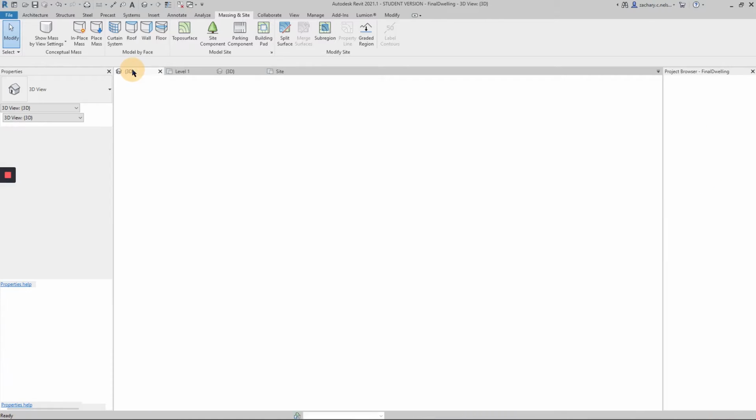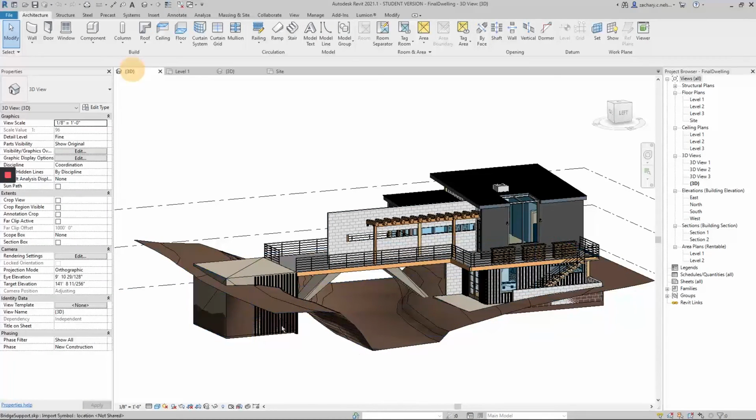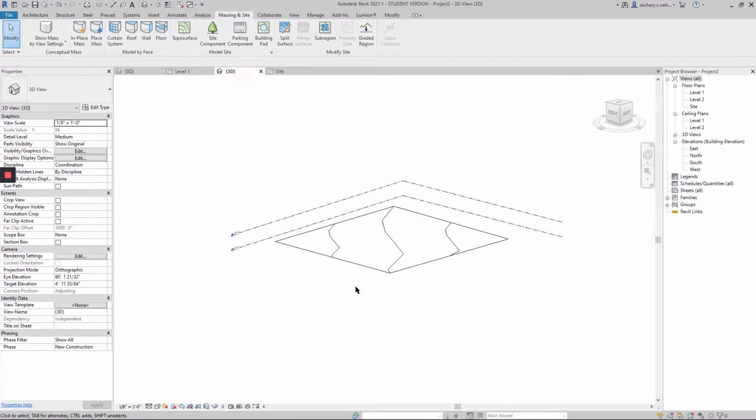So in my project over here, you'll notice that I can see everything in color, and the ground is brown. And I want to be able to see that in this project as well. So if I want to see colors instead of just seeing black and white lines, I'll go down to these icons along the bottom left of your screen, and I'll click on this little white box here in 3D that says Visual Style: Hidden Line by default. Then when you click on that, that'll bring up a drop-up, I suppose, and I'll go to Shaded, and now it turns brown. And so all the walls, floors, and things that I draw now will be in color rather than just everything being black and white. And it's a little bit easier to see in this way, in my opinion.